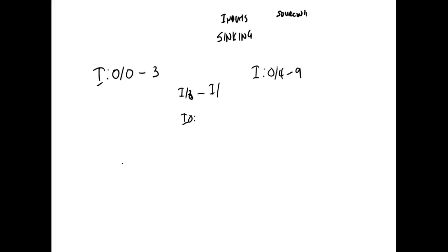The MicroLogix has a DC power supply on board, so the inputs are 24 volts DC, which is standard. So what do we do, guys, if I want to hook them up for sinking? On the same side, we have a DC power supply with one terminal labeled plus and the other labeled minus.